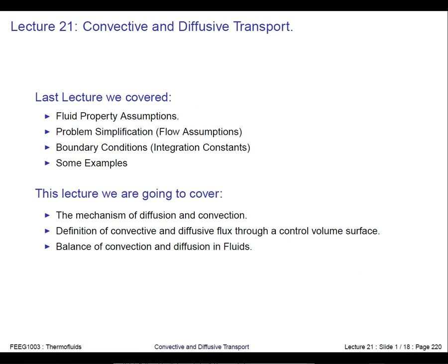So this is very useful compared to something like the Buckingham pi theorem, where you generated the non-dimensional numbers and worked out what the relevant non-dimensional numbers are for a particular problem. But the issue with the Buckingham pi theorem is that you had to know what these non-dimensional groups were to recognize them. So you actually derive these non-dimensional numbers from the equations themselves in this process. And this allows you to understand what's going on.